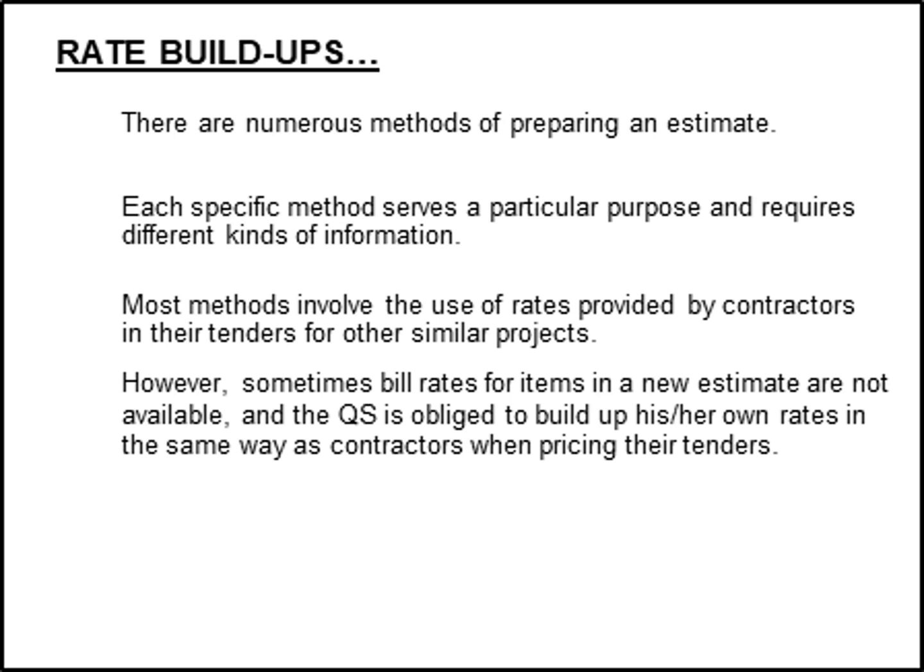What's not included in your elemental estimate and subsequently your rate buildup. So the main thing about the rate buildups is you're taking existing rates and amending them to be in the correct unit for your estimate. So there's numerous methods of preparing your estimate. Each specific method serves a particular purpose and requires a different kind of information. So sometimes you will have the information available, sometimes you have to build up your own rates, etc.